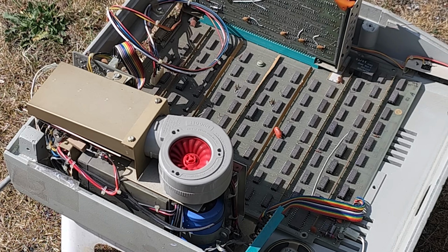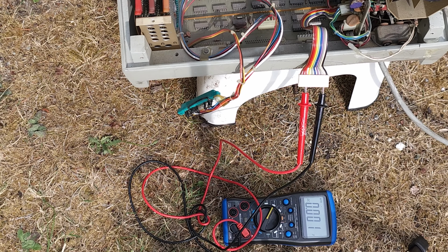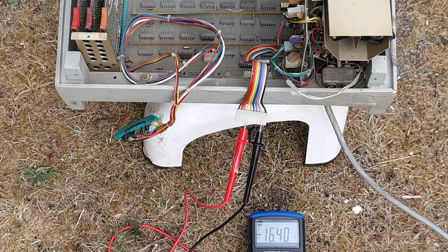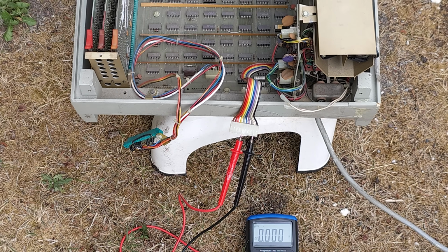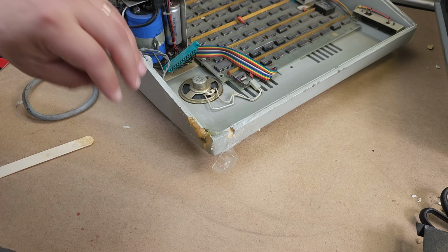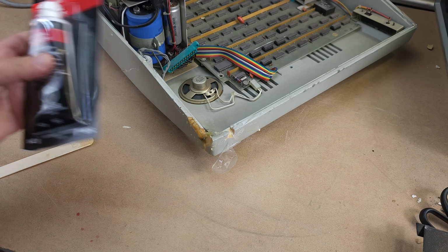It's actually very sedate. Now that I'm feeling brave, I've powered up the power supply and I'm testing the output voltages to see if they look sane. I do manage to find some that make sense, like there's plus 5 volts here, minus 16 volts could be legitimate if it's being regulated down to minus 12 or something. There's also plus 16 volts on another pin. But some pins don't have any voltage at all, and that's got me worried something in the power supply is dead. Anyway, putting that aside for a moment, back to fixing the chassis.